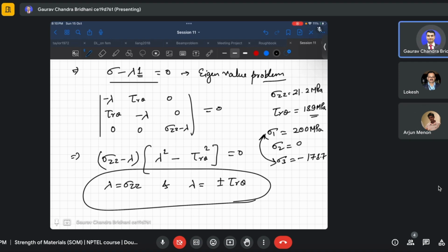Yeah, so actually, when we come to design stress, right now what you are doing is finding the factor of safety. But in case of design, the factor of safety is always given. It is not something to find. Suppose for a particular part, like a crankshaft, the factor of safety is defined as 4. For that material, you know the yield stress.